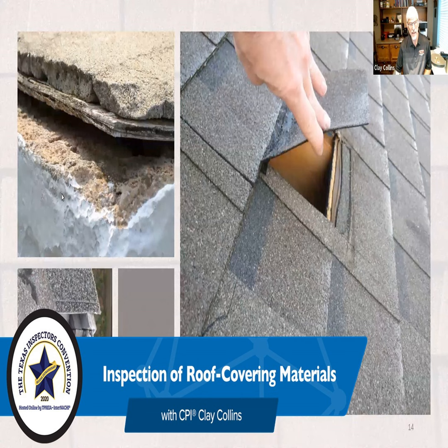Over here on the left, you can see 2 nails close together, but down here you see they're much further apart. And it entirely depends on the area that you're decking. Here, obviously a problem. It looks like in this particular case, they did not leave that 1/8 inch gap, and they didn't even bother to hammer it down flush.